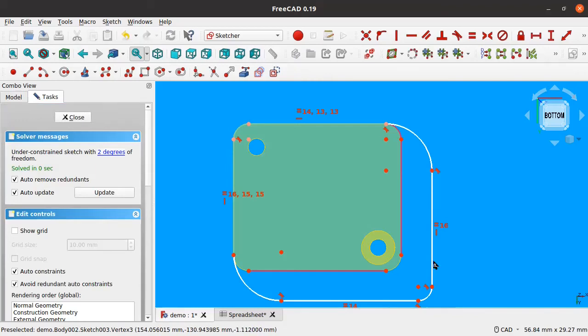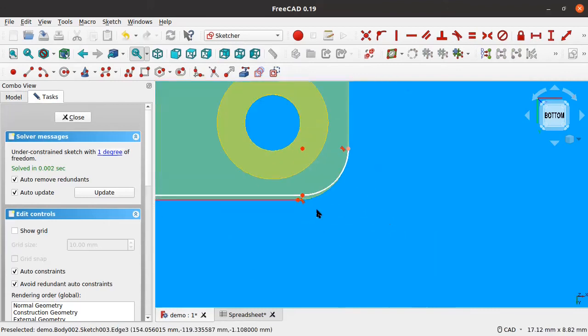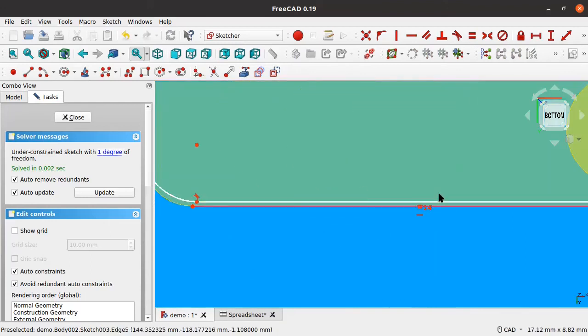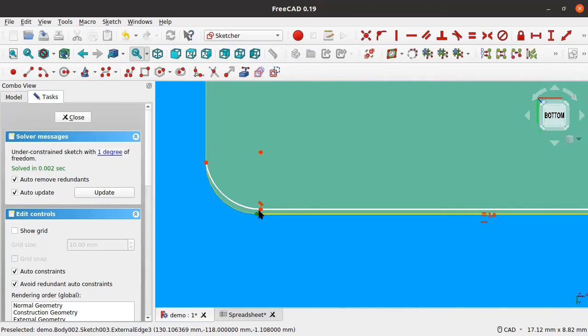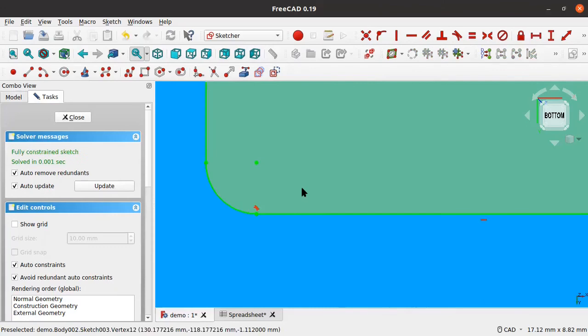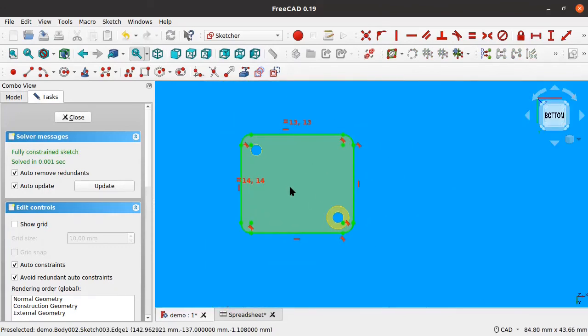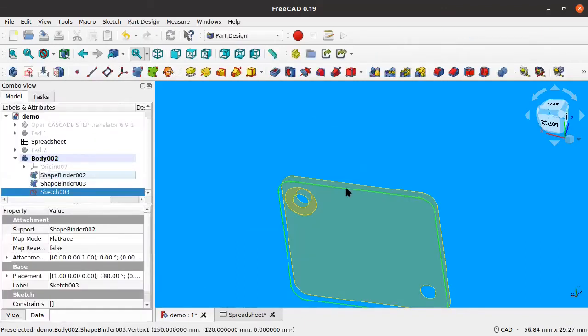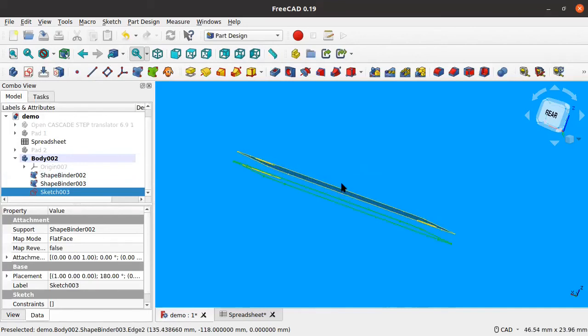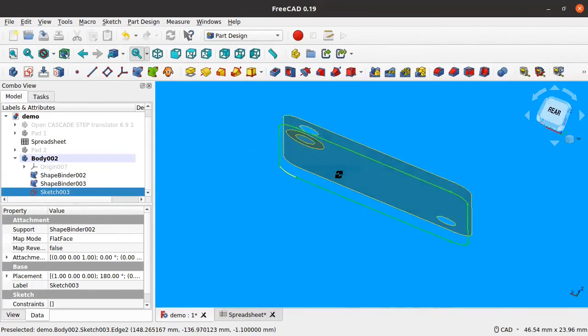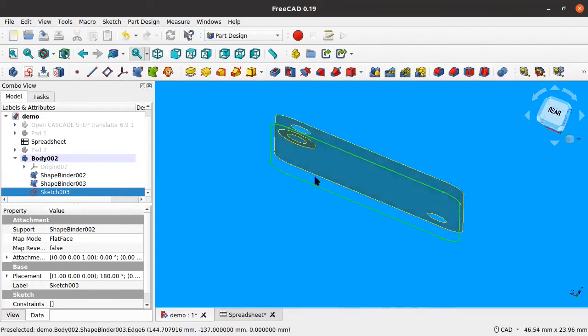And it really makes sense to do it slowly at first, because FreeCAD sometimes can get very crazy about constraints. And the general rule of thumb in FreeCAD is to try to keep your sketches as simple as possible, and then build on top of them, on top of the objects that you create from them.